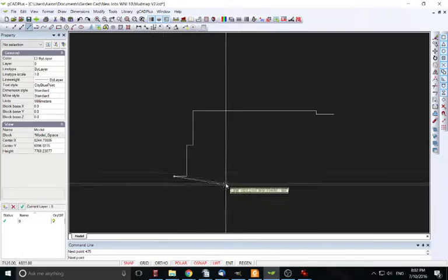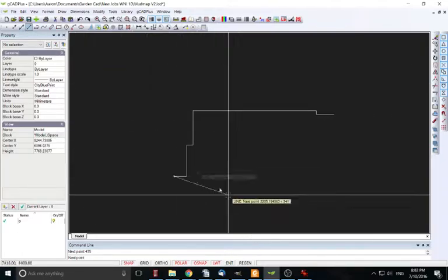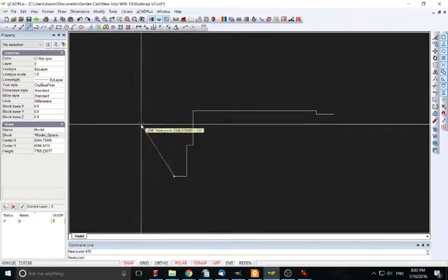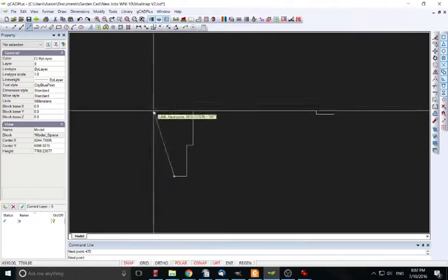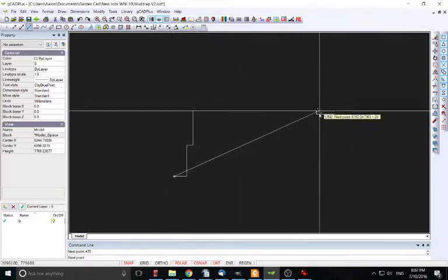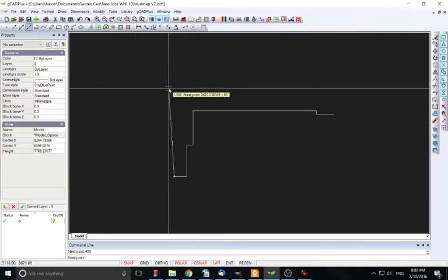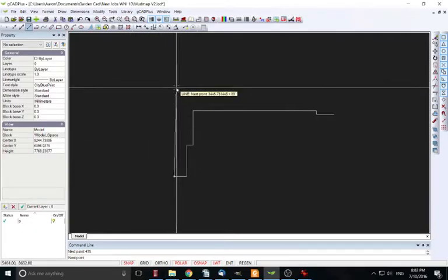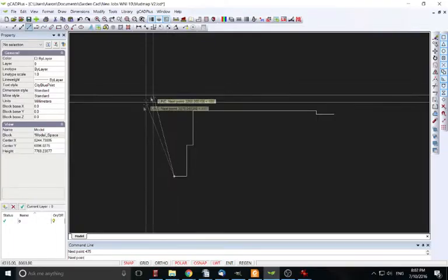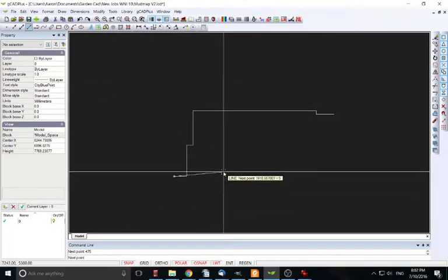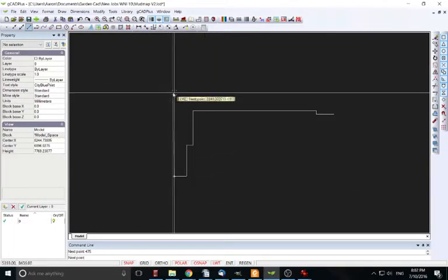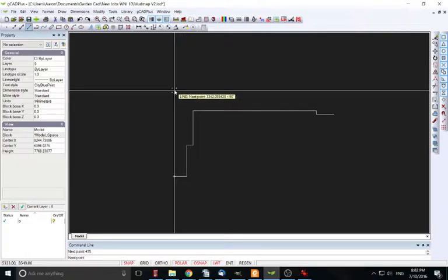And there's no real need to actually keep going line tool, line tool. Just direct the mouse roughly to where it's got to go, as long as it polar tracks onto it, because everything's going to be right angles here. You're just turning left or right as you go around. There's no curves. There's nothing much to work out. Just polar track to 0, or 90 degrees or whatever it is on each of these. 0, 270. 0 in this case is west or east, I should say.